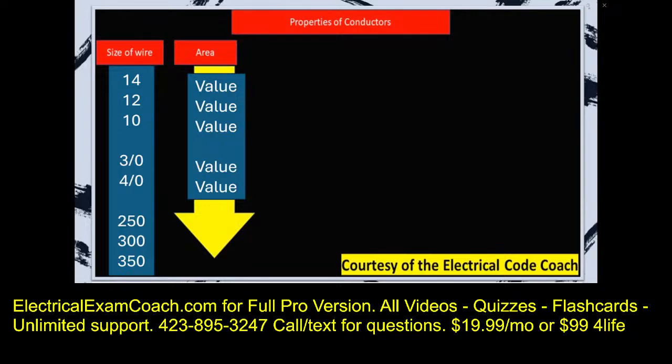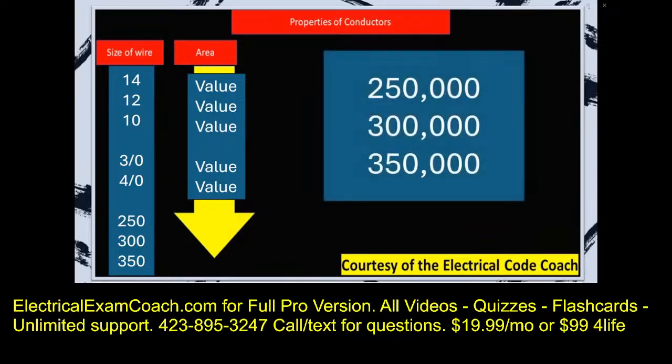You'll notice when you get down to 4/0 that the values stop. And the reason is because the left-hand side of this table, the 250, 300, and 350, are already showing you what the circular mills are in KC mills. So we have 250,000, 300,000, 350,000. So once you get past 4/0, you're going to get into 250, 300, 350, and all you have to do is add on the 3 zeros.